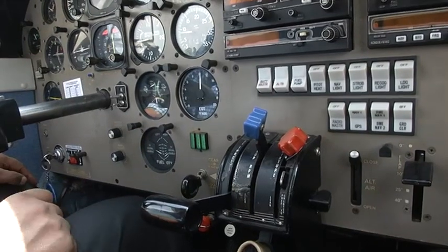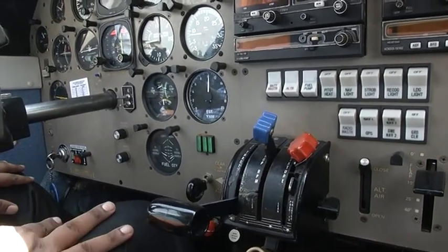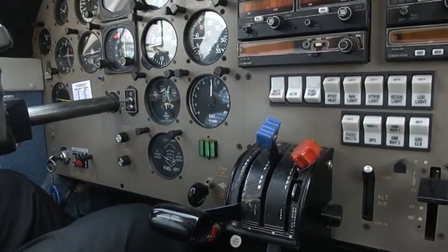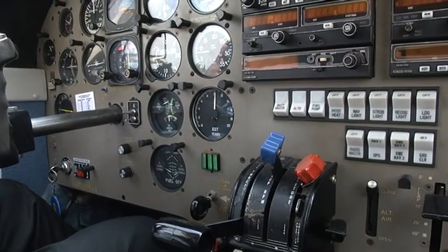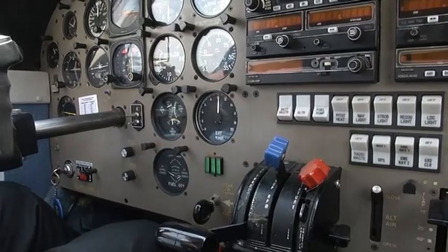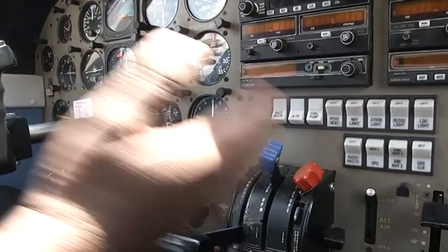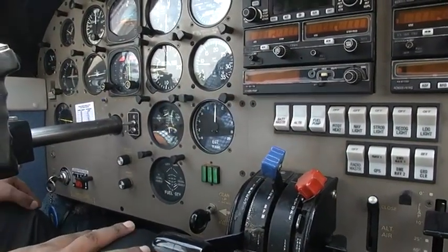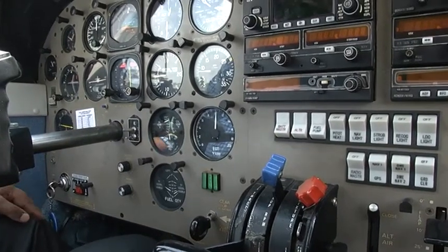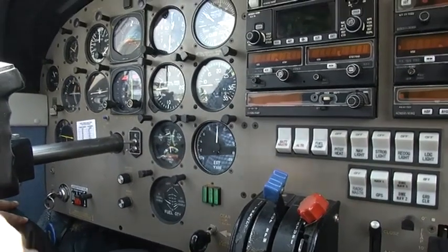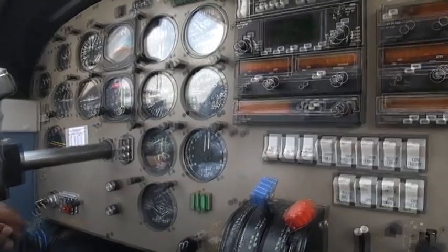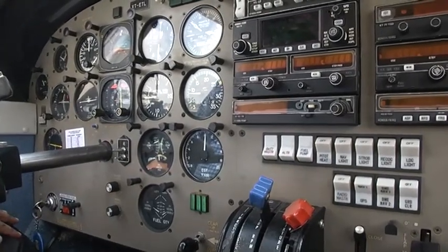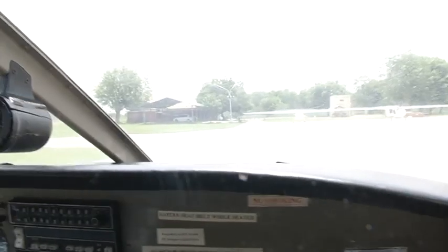engine doesn't cut off. Now with this, we have checked the full power being generated by the engine, we have checked the ignition system, we have checked the propeller system, we have checked the mixture system, and now we will taxi the aircraft. We will show how the aircraft is taxied and how do we turn the plane on the ground. As we had put the parking brakes on earlier,